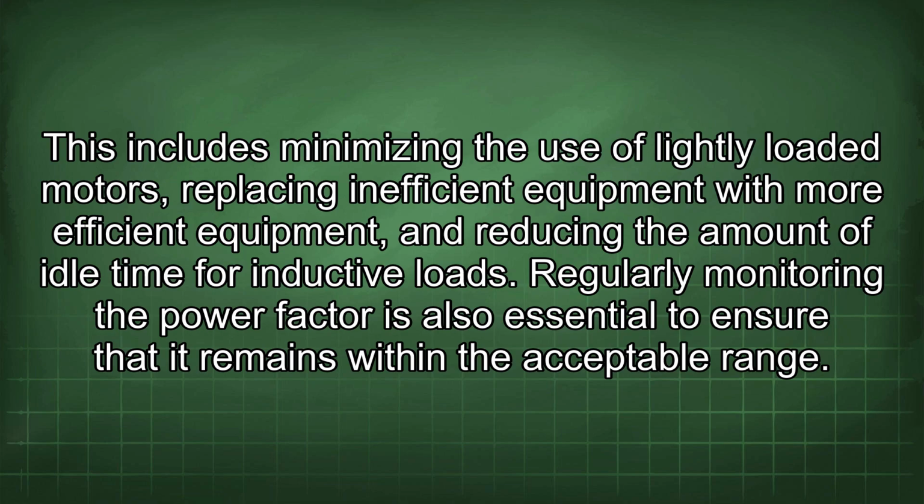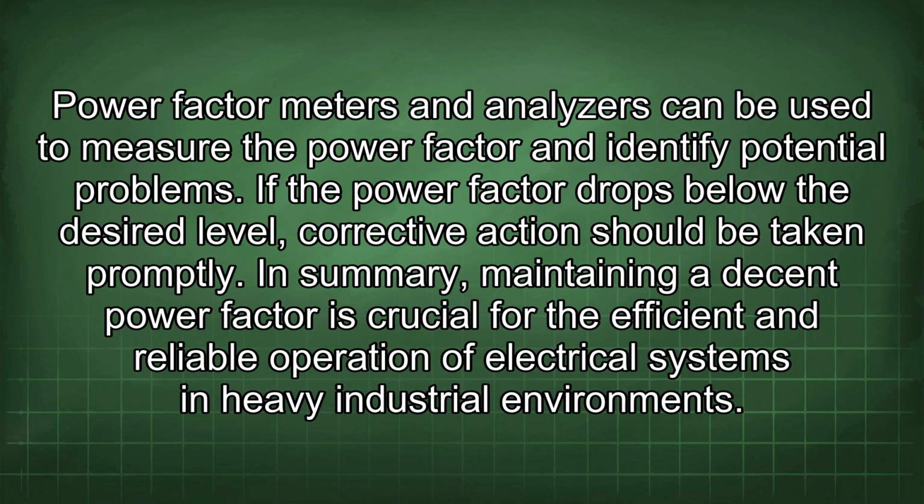Regularly monitoring the power factor is also essential to ensure that it remains within the acceptable range. Power factor meters and analyzers can be used to measure the power factor and identify potential problems. If the power factor drops below the desired level, corrective action should be taken promptly.